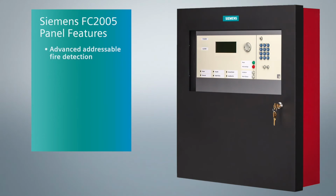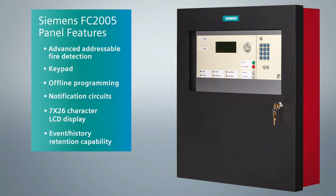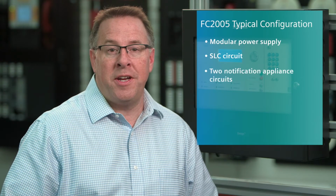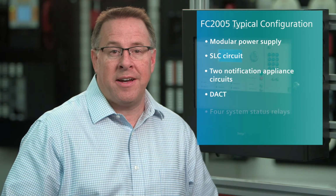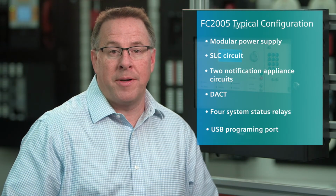The FC2005 is a compact but powerful standalone fire control panel. It features advanced addressable fire detection, keypad, offline programming, notification circuits, a 7x26 character backlit LCD display, and event history retention capability. Its typical configuration includes a modular power supply, an SLC circuit, 2 notification appliance circuits, DACT, 4 system status relays, and a USB programming port.